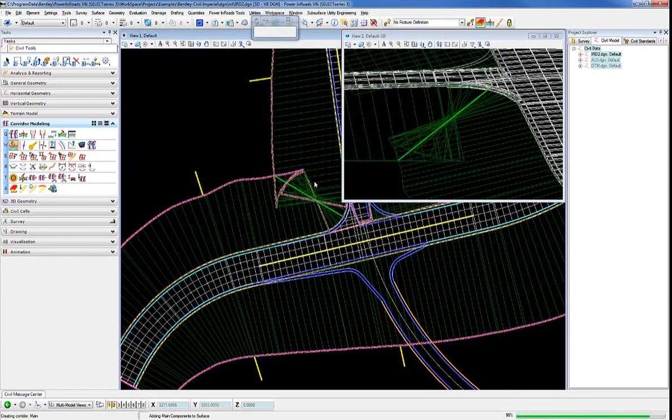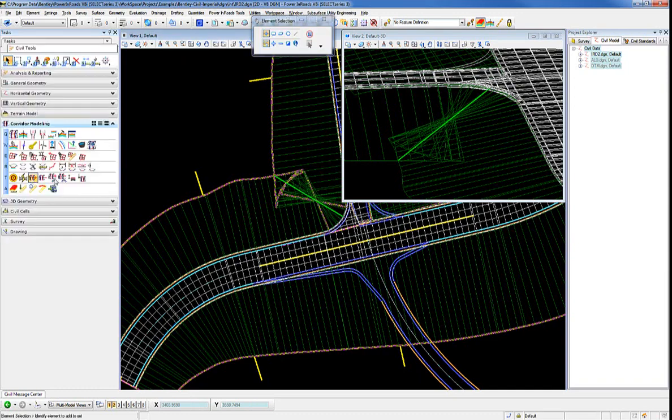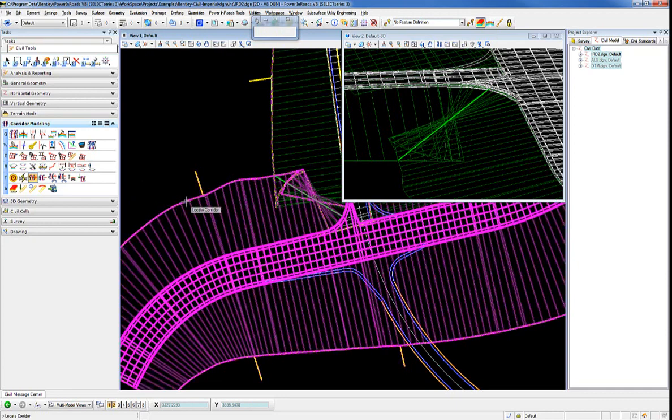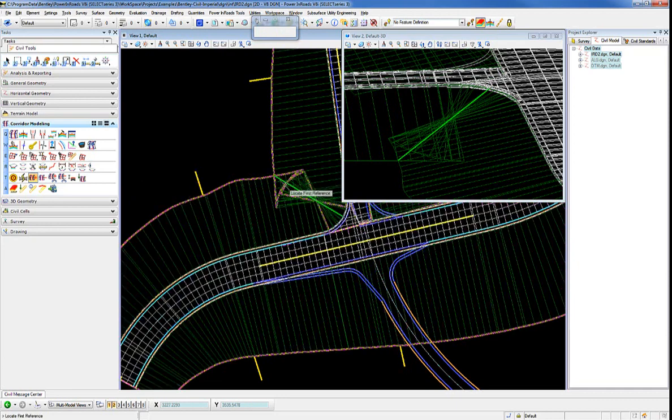So the last thing I have to do is simply add this line as an external reference to both of the corridors. So let's click on that. We're going to say add external reference. It'll prompt us to locate the corridor and then highlight the reference. Reset. You'll see as soon as I do that, my corridor will reprocess and we'll see that end condition there solve.